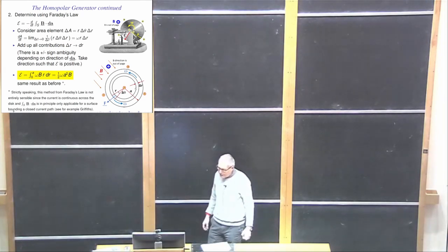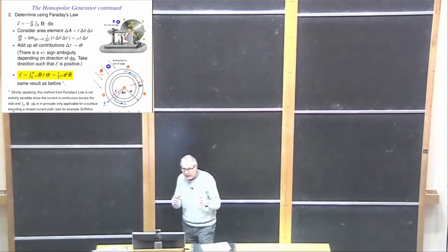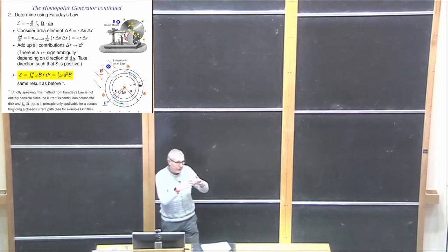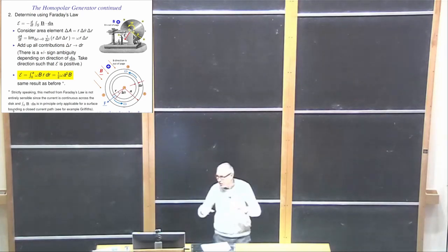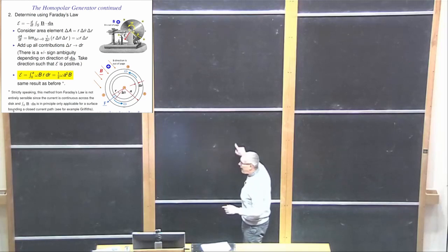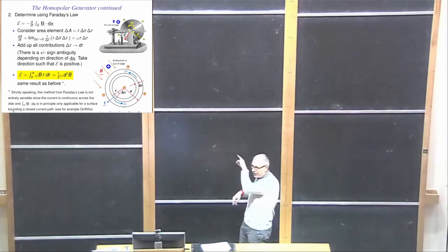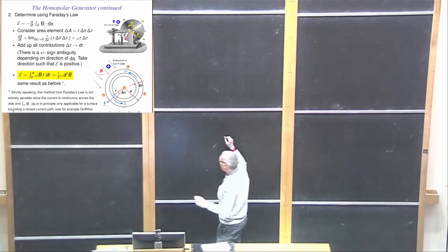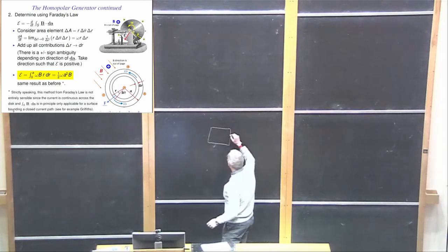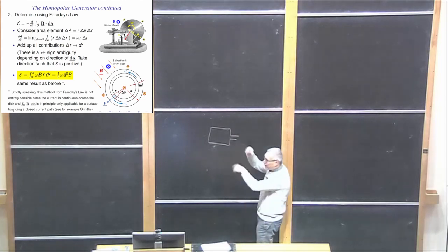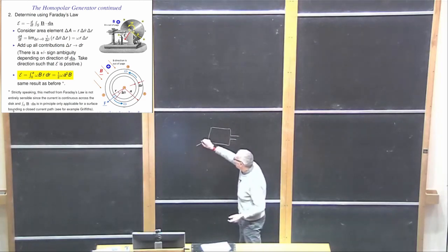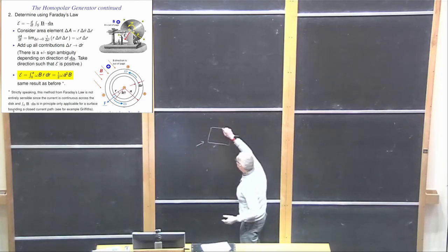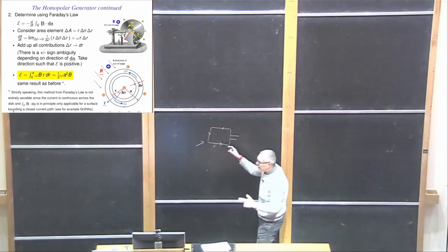But the point is that this method of flux linkage works for the area inside a circuital loop. So if you've got, which I'm going to do next, a wire which is rotating in a magnetic field, or a wire that's being pulled out of a magnetic field, then this loop can take a current.